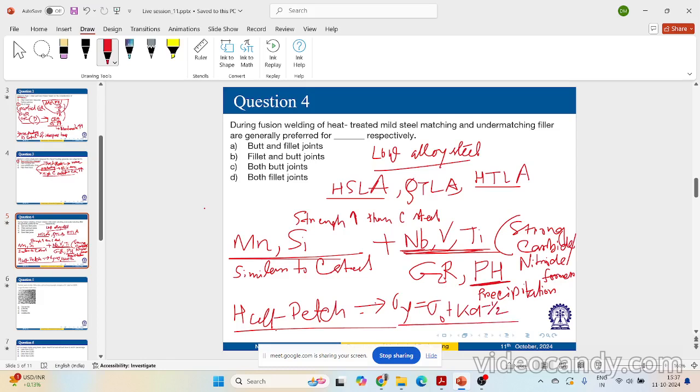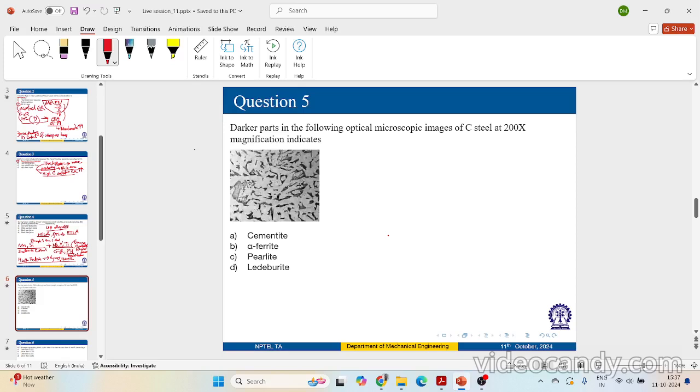It will give you the relation between yield strength and the grain diameter. So more refined grain structures, more fine grain structures, yield strength will be much higher, right? Okay. So that will increase the strength and toughness at the same time. The reduction in grain size. Now this is interesting because normally the toughness of steel decreases as strength increases. So if you are increasing your strength, you are compromising the ductility, you are compromising the toughness. But over here, this is interesting that it will increase both strength and toughness at the same time.